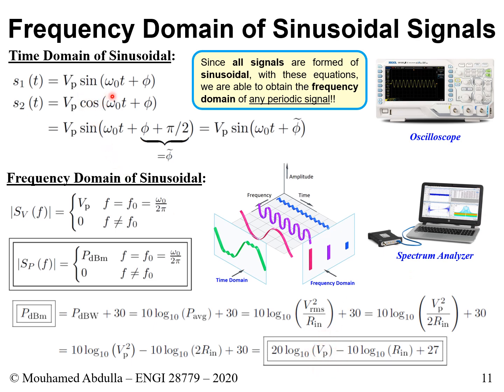What else do we have? We have the radial frequency, omega naught. Where is omega naught here? It's where this spike will appear. So this value where it appears is omega naught if we're talking about radial frequencies. But usually we present it with frequency, and the same thing with a spectrum analyzer: the x-axis is frequency, not radial frequency. So we simply divide by 2 pi, and therefore omega gets replaced by f.